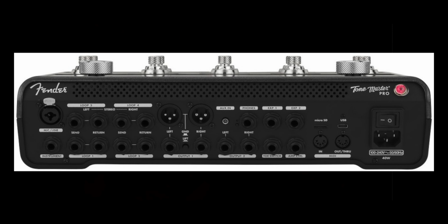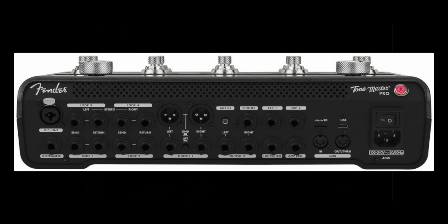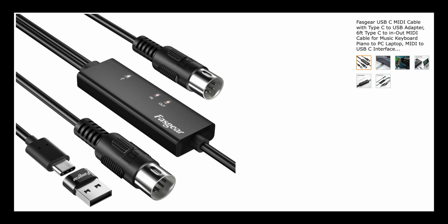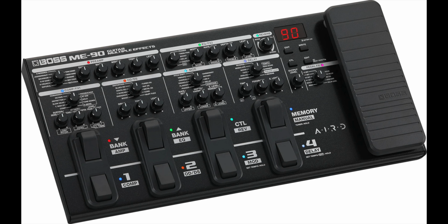Another thing worth mentioning, the Tone Master Pro sends MIDI messages using the 5-pin MIDI out port, not the USB port. Hopefully that will get updated at some point, but right now your external MIDI gear will need a standard 5-pin MIDI port in order to connect to the Tone Master Pro. You can also get a MIDI to USB converter cable, but those require power at the USB jack. For example, a Boss ME90 can't connect to the Tone Master Pro via MIDI because the USB-C jack on the